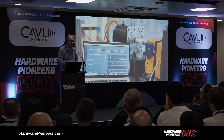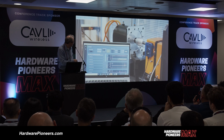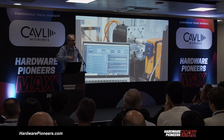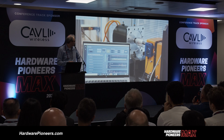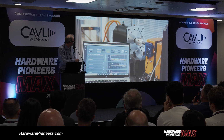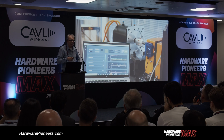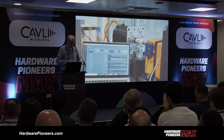By the way, with our sensor, we are measuring all the 3 axes, and in this case, the top one here also has the gravitational force. So that's the reason why it's situated in this 1G level of values that we get out. But this can also easily be filtered out. And again, when we were putting the motor to run slower, you can see that the vibrations went down, and also now when we stopped, it completely stopped. Usually the Z-axis is the strongest one, because it's pointing towards the load in this case.